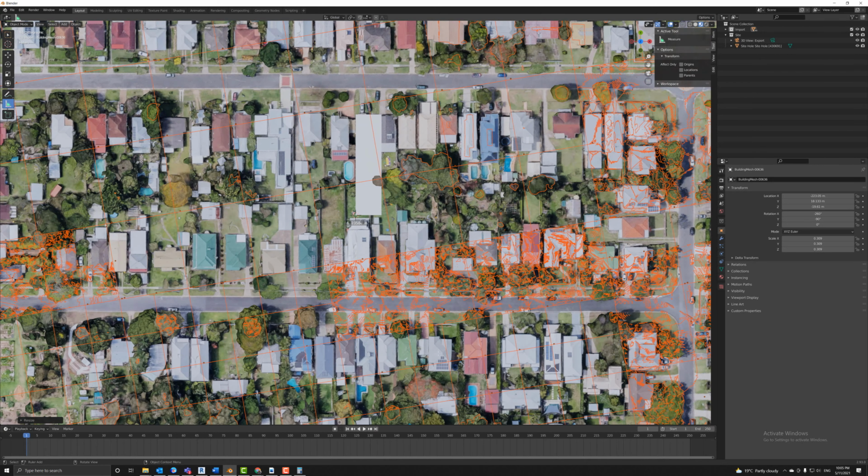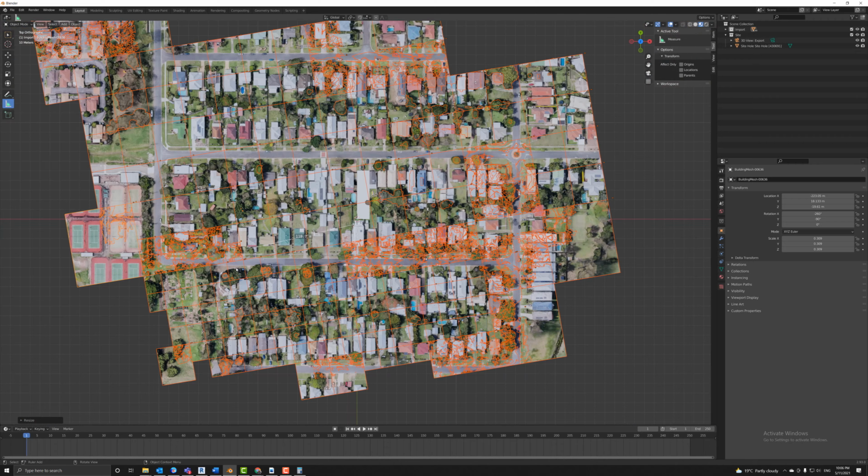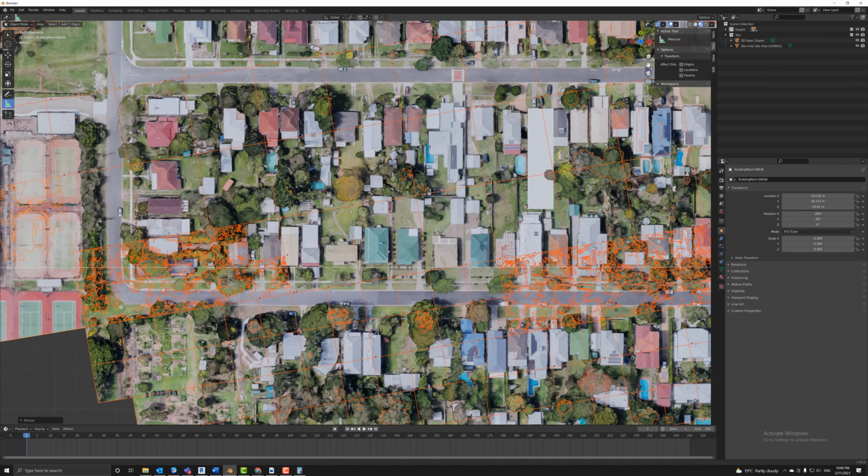But I'll use my selection tool to get the entire thing again. I'll just hit S for scale, and then I'll type the number that was on that calculator in and hit enter. You can see me typing it in the top left corner there. Hit enter, and now it's scaled up. So I'm just going to drag this measure tool back to those locations now that it's scaled and see how accurate it actually is.